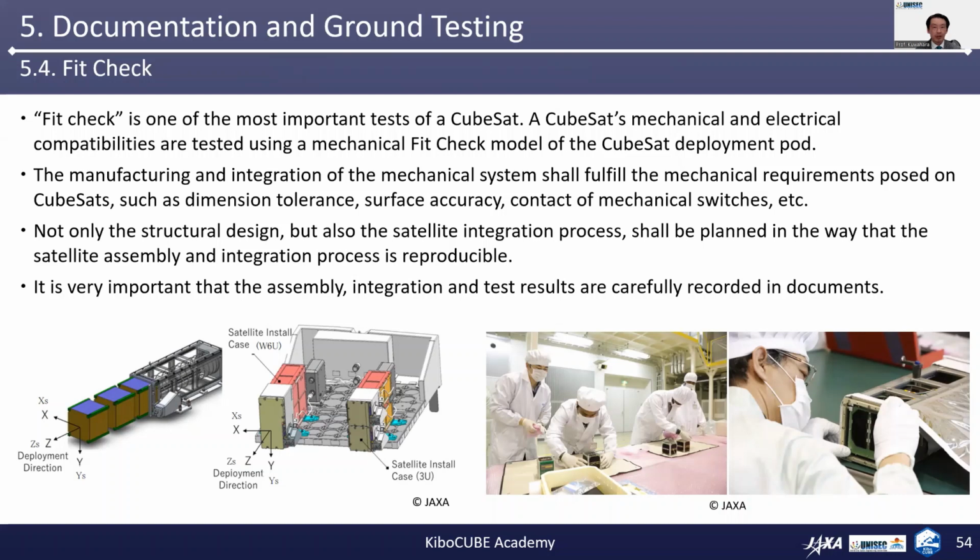One of the most important tests of a CubeSat is the fit check. So in this test, a CubeSat's mechanical and electrical compatibilities are tested using the mechanical fit check model of the CubeSat deployment pod. The manufacturing and integration of the mechanical system shall fulfill the mechanical requirements posed on CubeSats, such as dimension tolerance, surface accuracy, contact of mechanical switches, etc.